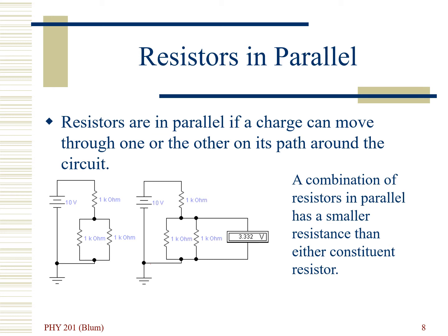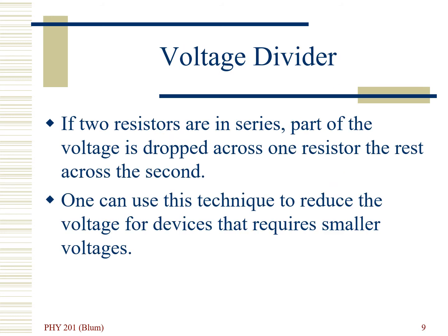And so then that parallel combination has a smaller resistance and thus requires less of the energy. So more of the energy is used in the top 1 kilo ohm than in this parallel combination at the bottom. Our simplest version of a digital to analog converter is going to be a voltage divider.